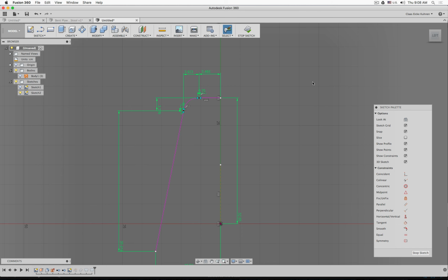So with the trim command, the software basically extrudes this sketch along a path and then cuts. Well, I can also build the surface, so I extrude it, and then I use the mirror command on the surface and build myself the other part. So I only have half a sketch, make half a surface, and then duplicate the surface. So in the end, I get exactly the same result.